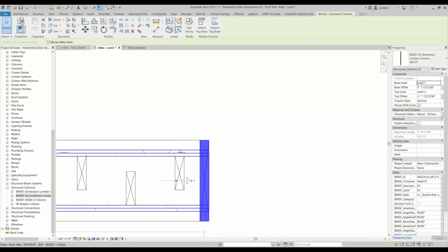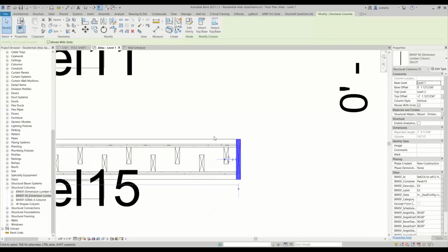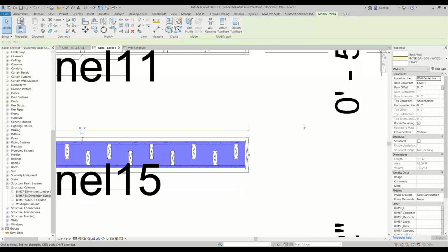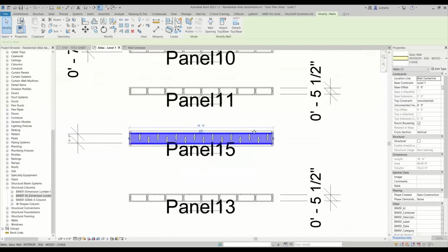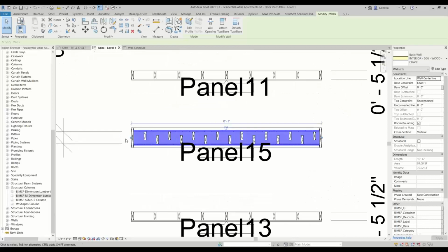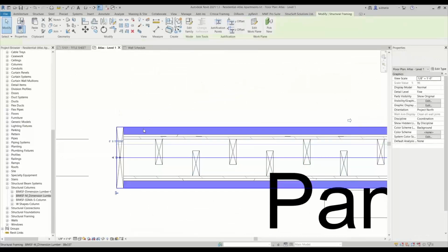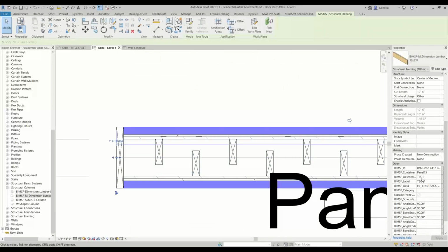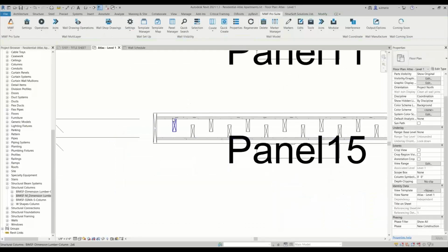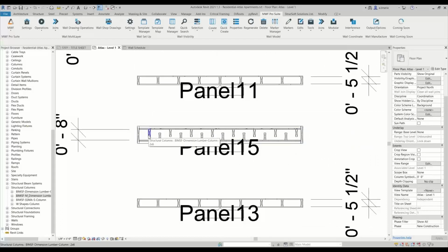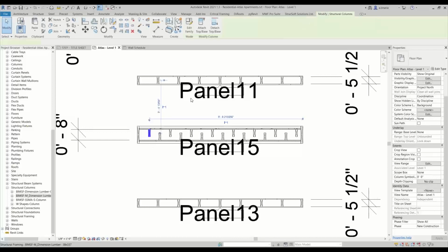That means the walls I drew are probably not the same size as what was specified in the other project, right? So what I can probably do is either double check if I'm supposed to use the same template, or maybe change my end studs and my top and bottom tracks, because you can see that's my bottom track right there sticking out of the panel. So I will just need to double check that template, and then once I do, I can save it over top of the existing one.